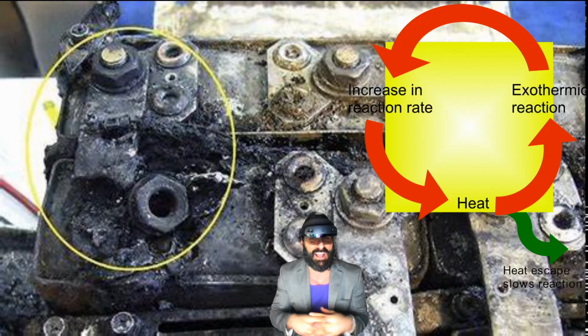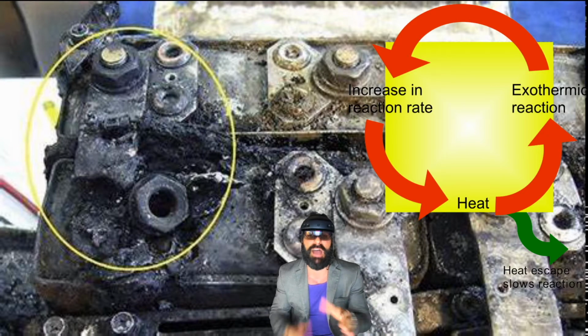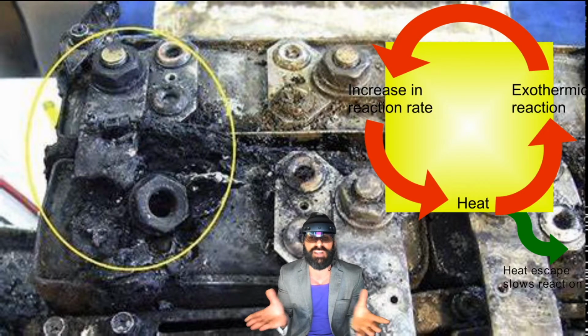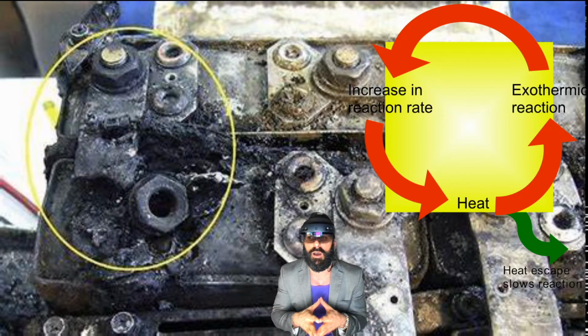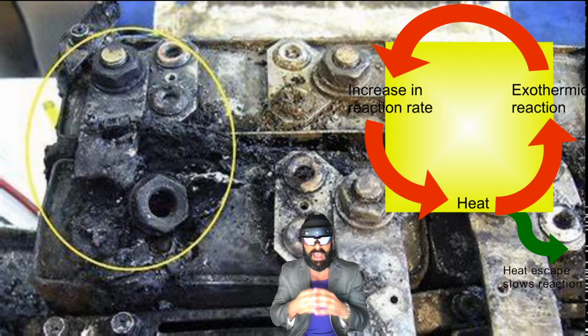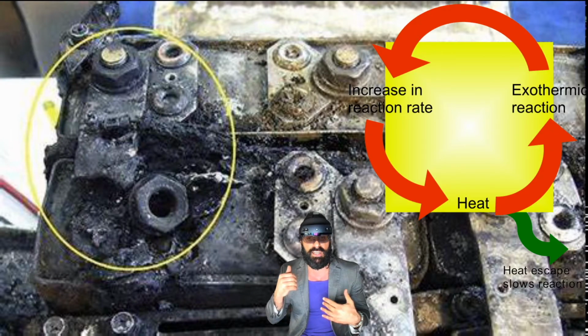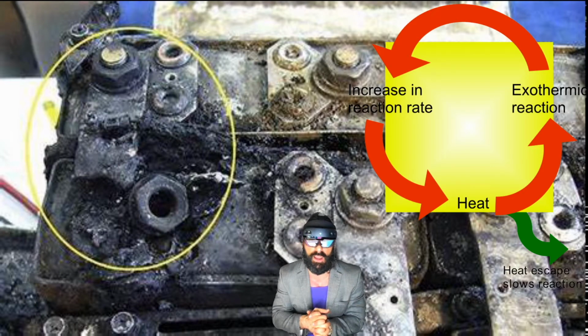You can even use Raspberry Pi stuff, which is something I'm testing now, and what you want to do is essentially trip that if it goes over 1 amp or 750 milliamps or 1.5 amps, whatever that signal threshold is that you programmed into the monitoring system, you want it to trigger. Now remember that UVR and shunt trip, that voltage is coming from the UPS. So it's either 48 volts or 24 volts, and it's either being constantly supplied or it's not, and the breaker just closes, and if they need to trip it, they send a signal out to the normally open or normally closed contacts and it'll trip the breaker, okay? So all of this stuff can be integrated, and it's very important that it should be.